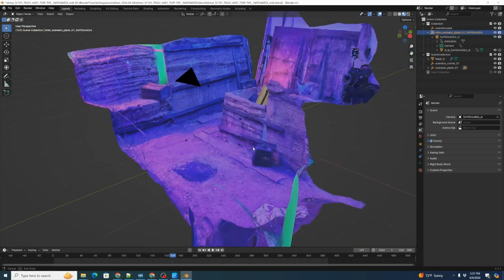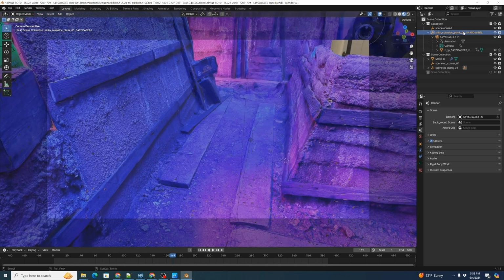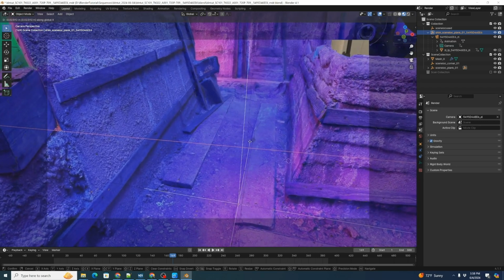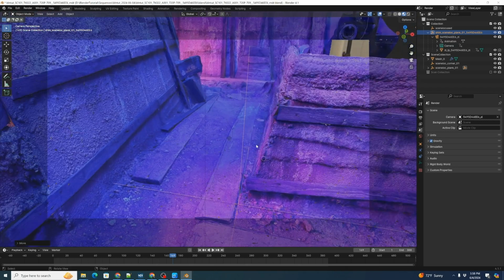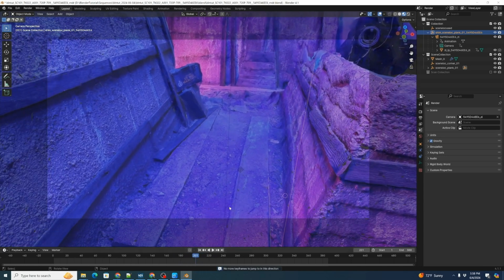So here's our 3D shim. This is located exactly where the scene locator is, but it's not the same as the scene locator. The interesting thing now is we can move it. If we frame up with 0, and we have our shim located, if we hit GX, we can actually move our camera track back and forth in the scene, and wherever we put it, it'll still track finding the scene. So we can actually adjust where our camera tracking origin is after we shoot, which is quite useful.